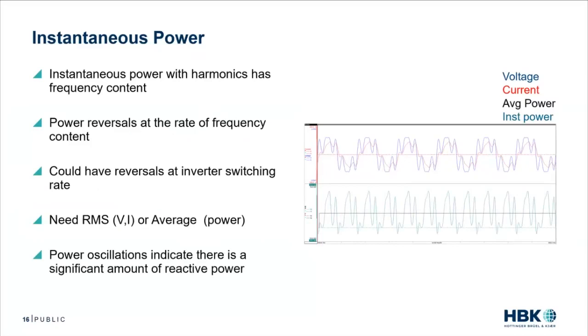So we'll start off with our instantaneous power. We'll start at the same place we did previously. So what we see is I've got my power in my aqua, and we can see that I'm just taking P is I times V, and we get this really jagged waveform because that multiplied product is following the shape of those voltages and currents.